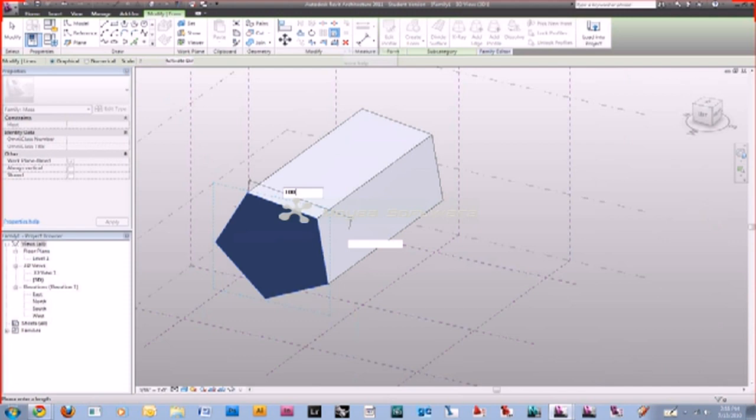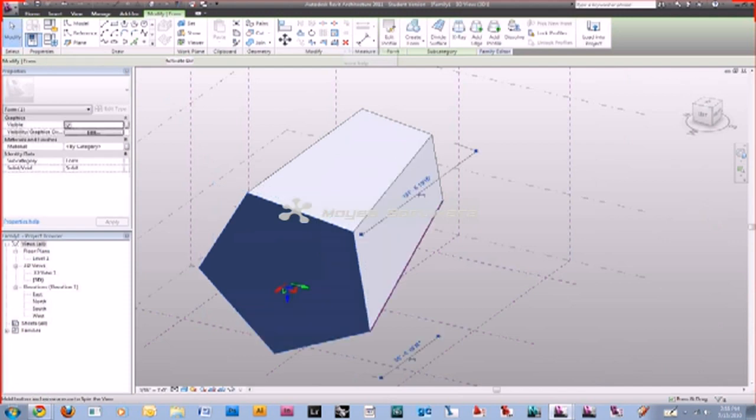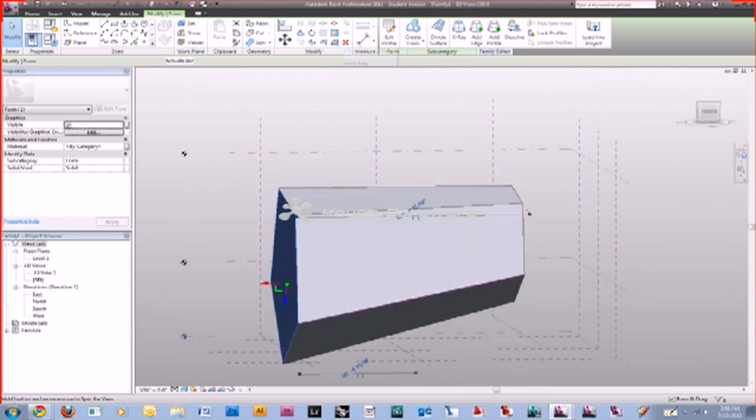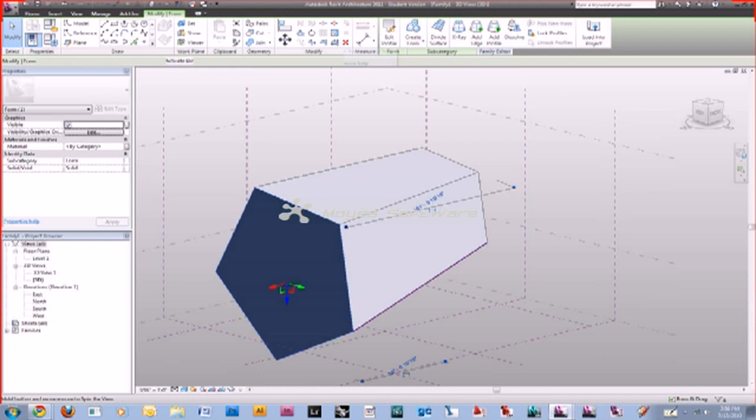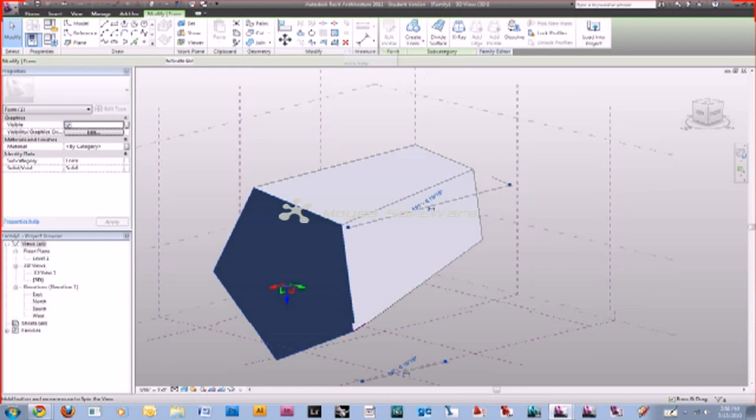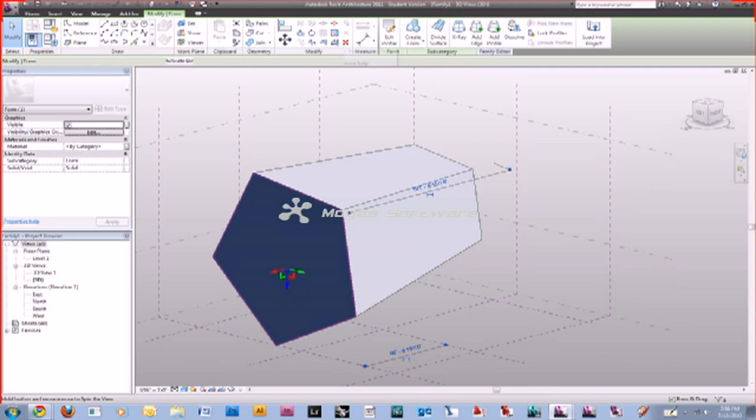That's another thing to take note of: in Revit, you don't have to hit the feet symbol. You don't have to hit the hyphen symbol. Yeah, the little thing. You don't have to hit the singular quote here. It formats the feet automatically.